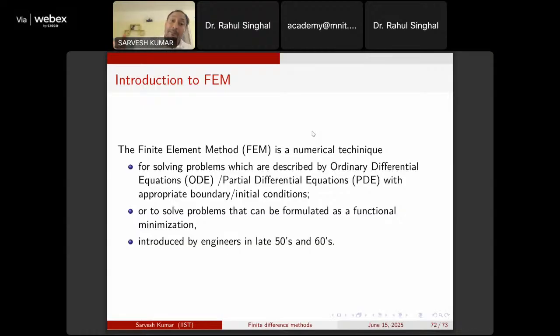Third, if your domain is complicated, a very complex geometry. Suppose you have a rectangle, perfect. You can have a rectangular grid there, right? You can have only a rectangular grid, as we have seen, and work with this. That means they are structured grids. If we don't have a structured grid, which is demanded by many domains, depending on what the domain is, then the finite difference method won't work there. Another problem, which somebody asked me about in the morning, is the smoothness of a solution. For convergence in the finite difference method, I need a very smooth solution.